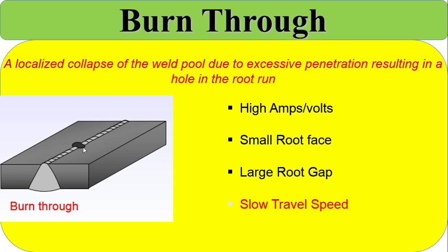So these four things are very important causes for burn through. Everything you have to maintain as per the WPS. Not like high amperage, high voltage. You have to follow the correct amperage and correct voltage to make the quality sound weld.